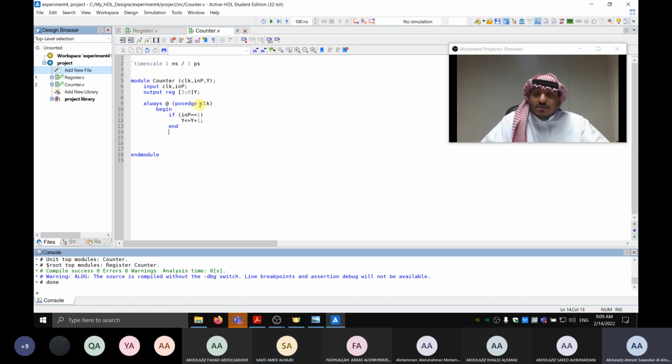Okay. So the first issue, as mentioned, you see, it says if there is a signal, you count up. Now, the first thing, you start the code. Now the code is running for the first time. Now there is an input signal, 1. And now it says y, the new value, is equal to the old value plus 1. Now the question is, what is the old value in that situation? It doesn't know. Do you see what's going on?